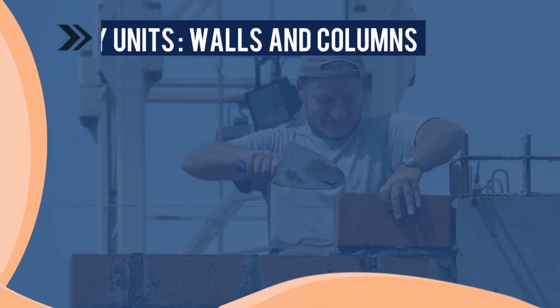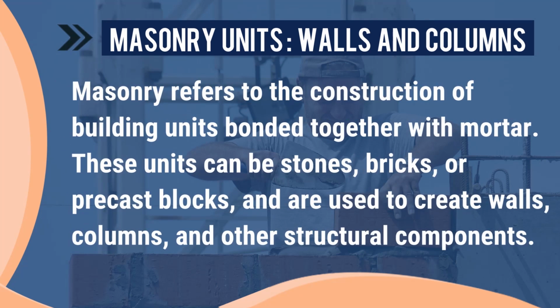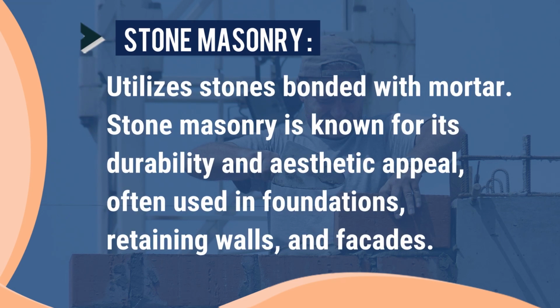Then the masonry units, which include walls and columns. Masonry refers to the construction of building units bonded together with mortar. These units can be stones, bricks or precast blocks and are used to create walls, columns and other structural components. First is stone masonry, which utilizes stones bonded with mortar. Stone masonry is known for its durability and aesthetic appeal, often used in foundations, retaining walls and facades.